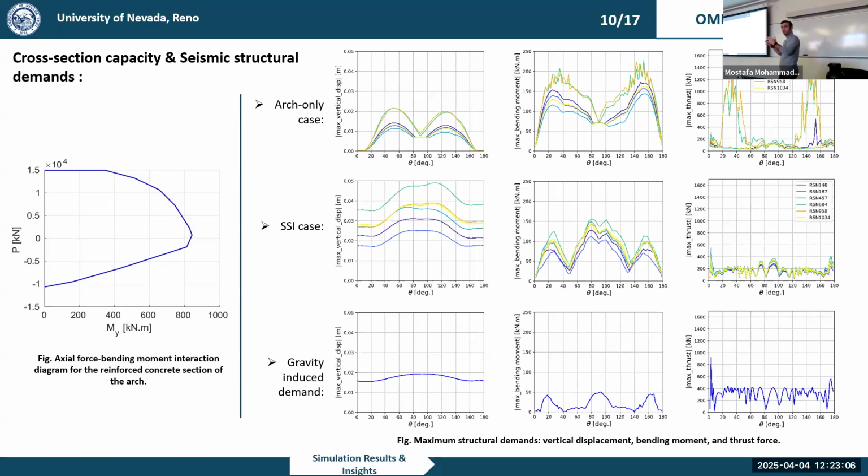So we are seeing that shift from the sides to the ground, and it makes the sides a little less steep. The same thing is happening for the bending moment, and for the thrust we see the same behavior but with much smaller values, because with the soil present, some of that thrust force will be taken care of by the soil shear strength and all those interactions.